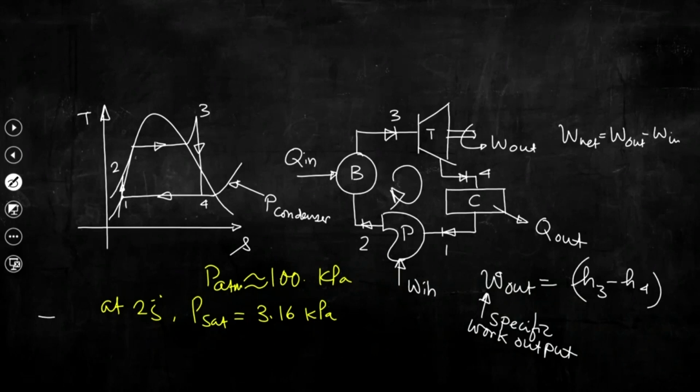So, that means the entire condensation process will be conducted at a pressure which is way less than the atmospheric pressure, and if we need to perform this particular process, we need this particular component, and that is the condenser. And if we do like this, then try to understand, say this is the pressure.